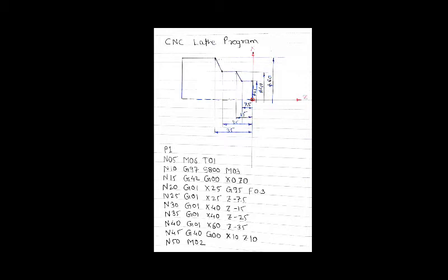Hence the nose radius or tool radius compensation is a function for automatically calculating and offsetting this error by setting the nose radius or tool radius value. There are two G codes for it. G42 is for nose radius or tool radius compensation right mode on, and G41 is for nose radius or tool radius compensation left mode on.